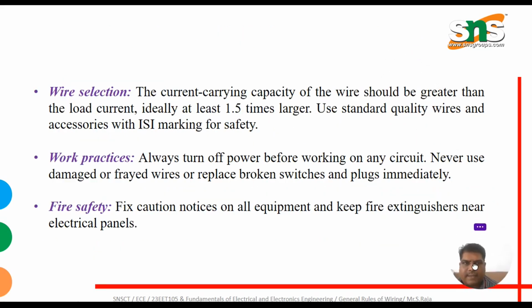Next, wiring selection. The current carrying capacity of the wire should be greater than the load current. Ideally, it is 1.5 times larger than the normal value. You can use standard quality wires and accessories with ISI marking for safety. Work practices. Always turn off power before working on any circuit. Never use damaged or frayed wires, and replace broken switches and plugs immediately.